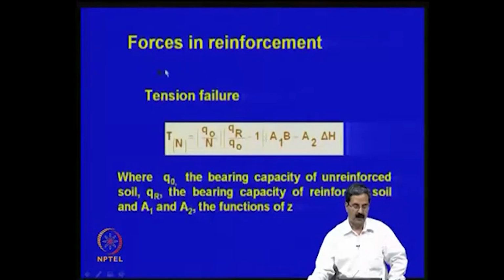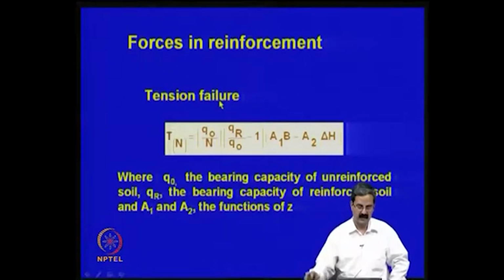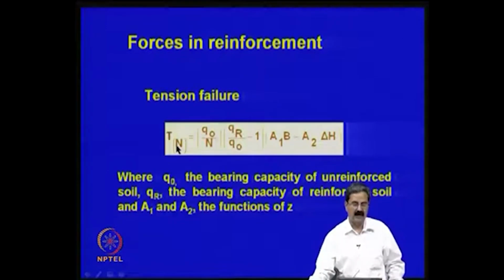And what we say is that you need to find out the tension force in the reinforcement. Actually, we have seen that it is in fact a function of how much tension is mobilized; I should have proper spacing and number. Say for example, this expression gives you the tension force in each member.